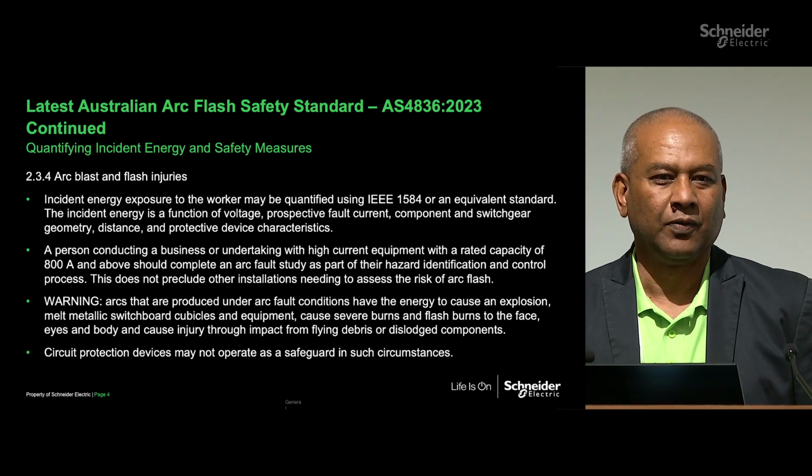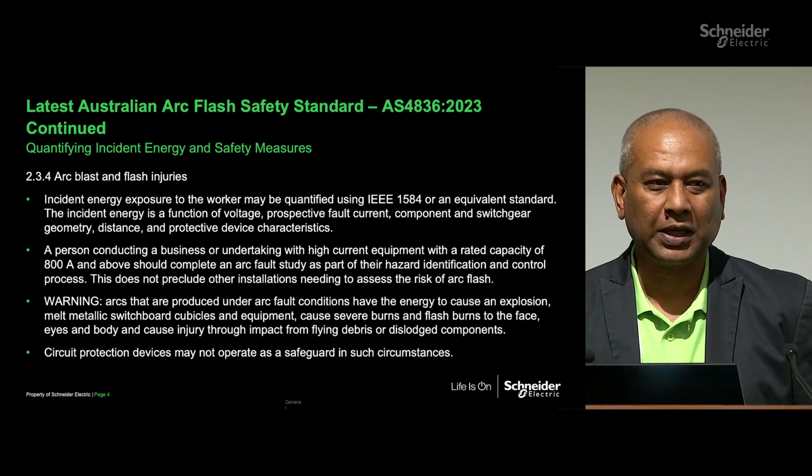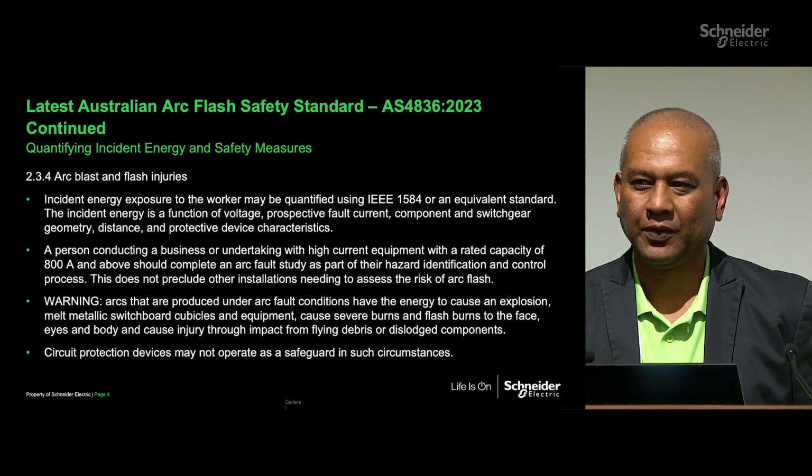You don't need to manually calculate with Excel files and all, which is what we used to do in the past. So there's good software tools like Schneider's ETAP software, and there are other third-party software that allows you to do what the IEEE recommends as a calculation of arc flash hazard. So my advice is, as a starting point, AS4836 for arc flash, even though it's a low voltage installation and working near low voltage standard, covers arc flash pretty well. So get that standard if you haven't got it, and let it guide you on arc flash.